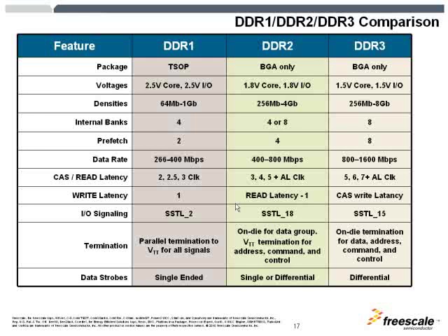Also, the I/O signaling has changed as the voltages have dropped. We're still using the SSTL in a different formation, which is different voltages. They're JEDEC defined parameters. Next, the termination has changed from DDR1 to DDR2 by introducing the on-die termination for the data and strobe.